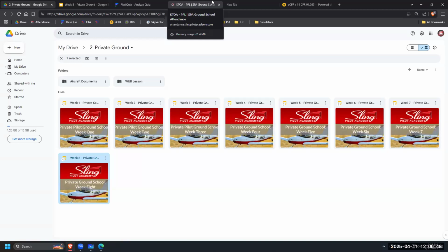Now in pilot terms, the descending blade is getting a greater bite of the air, pushing the plane to the left. What's that called? There's a descending blade and there's an ascending blade. P-factor. P for propeller. P for propeller.